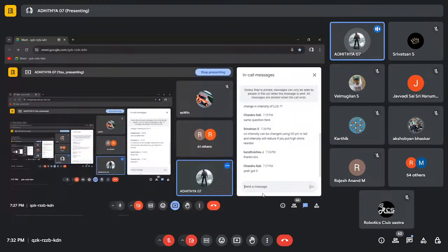So the left side is one motor driver, the right side is one motor driver. The second set of pins, from pin number 9 to 15, do exactly what I said just now. The only difference is that pin 16 is the connection for the IC itself. Every IC requires a VCC of 5 volts for its internal electrical requirements, so this is used for that.